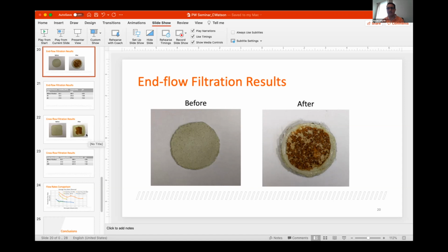The second thing, when you have your setup, your feed tank, let's call it, or this beaker is very small, and that typically would change the property of the constituents there. I would suggest using a larger volume feed tank, which would reduce the variability in the feed tank and give consistent properties of the feed to the membrane.